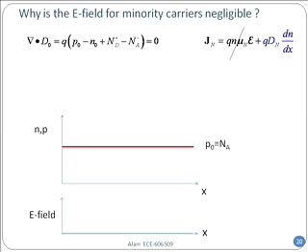Now, in equilibrium, I can also say that the minority carriers, which is the number of electrons, is equal to ni squared divided by Na in the extrinsic region, right? I'm assuming full ionization, not the freeze-out or intrinsic region. Okay. n naught is a very small number, right? For example, if p naught is 10 to the power 18, and if it is in silicon, what is n naught? 100, because ni squared is 10 to the power 20. And so, n naught is actually a tiny, tiny number. Fine, but it is flat, uniformly doped, and together they make the electric field zero.